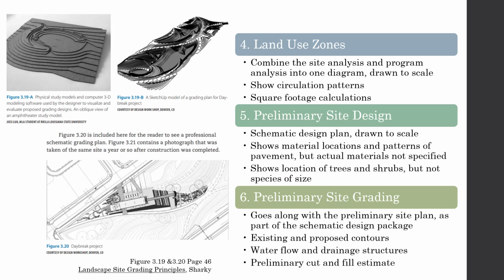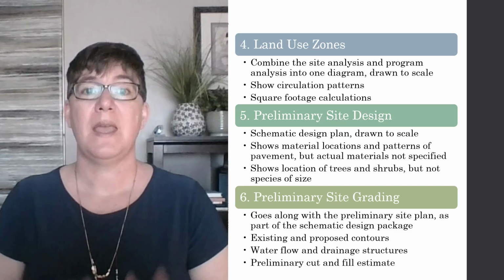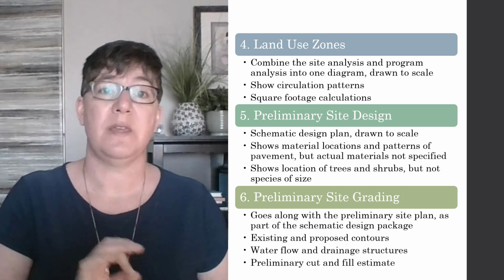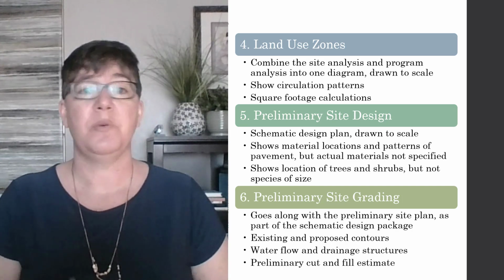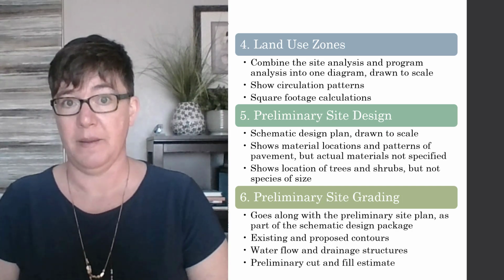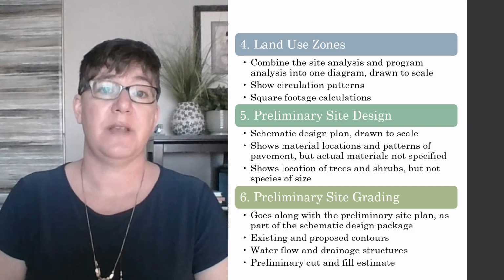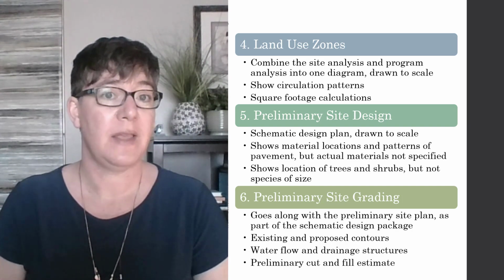Once you've made it through all of these design steps, it's time to prepare the schematic design package, and that's going to include both a preliminary site design and preliminary site grading, probably in the form of a schematic site plan and a schematic grading plan. And that's as far as we're going to go in this course. But as you know, in a real project, the next step would be to continue to develop this design and come up with construction documents and move into construction.